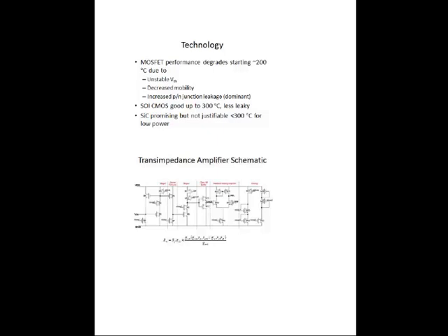And these devices here are just diode-connected biasing devices. Just for the information, we discovered that since we use zero threshold devices for operation, when temperature varied, these devices started not to behave as diode-connected devices, and bias levels shifted. We predict that this is the reason why this amplifier failed around 250 C or above.